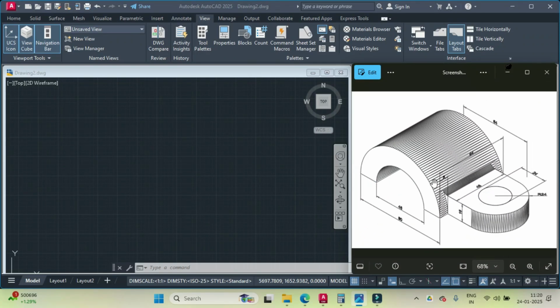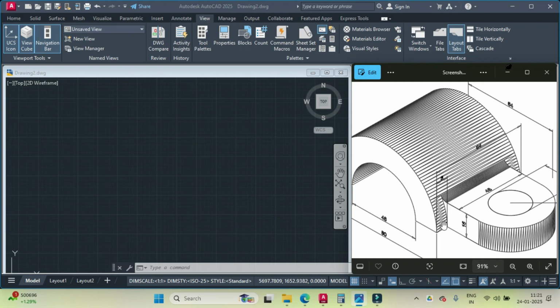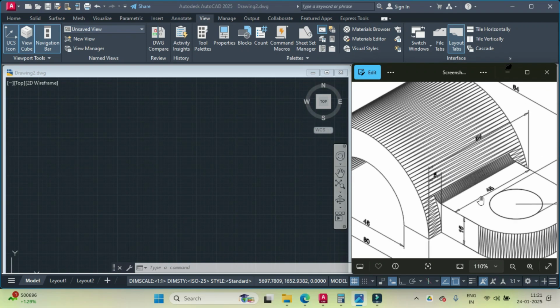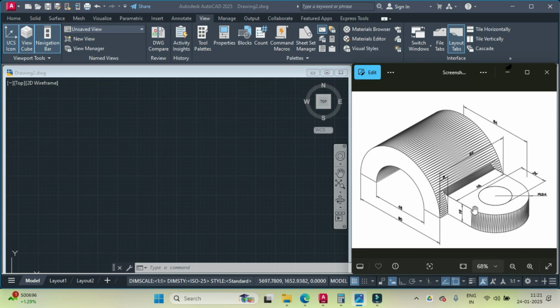Then we'll move the rectangle 8 units from the left side over here. Then we'll fillet this edge with a radius of 24. Then on the outer circle, we'll draw this circle of dia 24 and using push-pull take it downwards. And then we'll get a hole over here. With this, we finish the geometry. So let me show you how we'll proceed with this drafting.